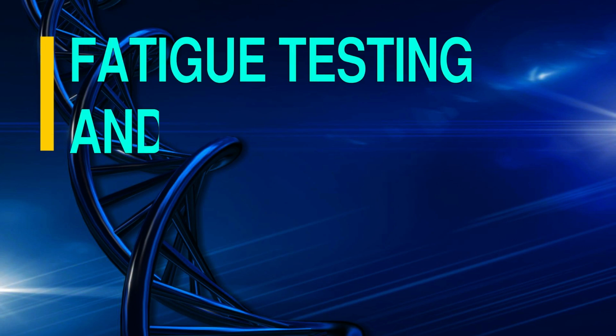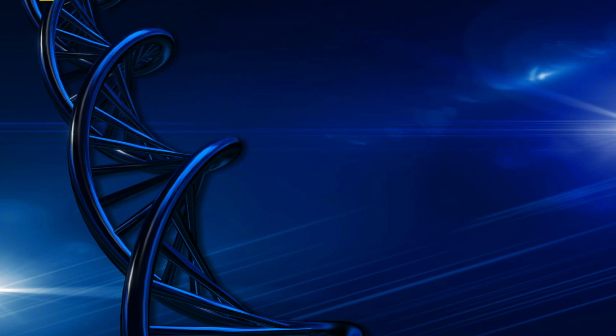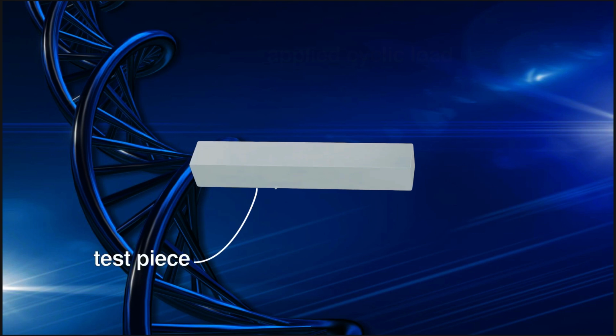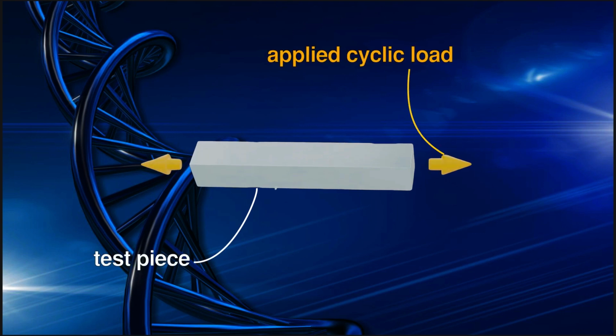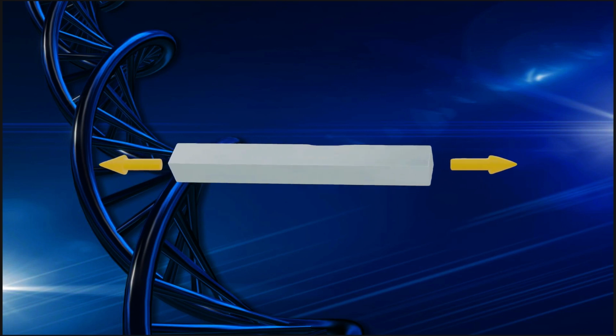Now, to figure out whether a component is likely to fail due to fatigue, we run a fatigue test. A common approach is subjecting a component or a test piece to a large number of constant amplitude stress cycles and counting the number of cycles until it fractures.